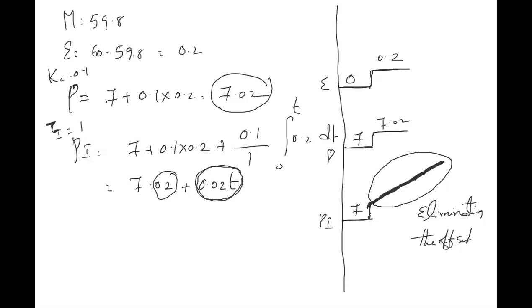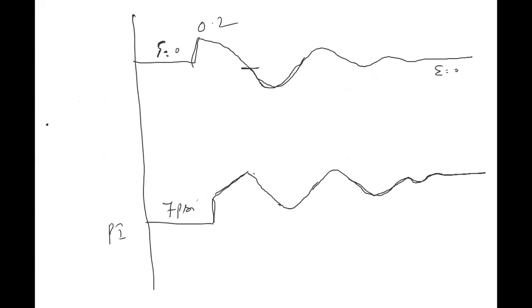So that is what the increasing curve is. In reality, my error starts at a point, then my pressure starts to increase, then the error slowly drops, and drops below zero to a negative error, then it will increase again. This kind of oscillatory behavior is there because you cannot put the control valve at exactly the right position. Let's say right now the control valve is 30% open and the system is at 60. Suddenly the temperature becomes 59.8, and you have to close the control valve. What is the correct closing? You don't know exactly.